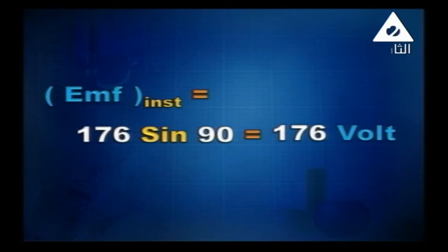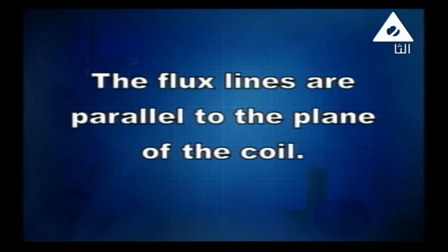Maximum EMF happens, yes, in the instant when the coil is in the horizontal position, where the plane of the coil is parallel to the field. Okay, so the flux lines are parallel to the plane of the coil. The coil is in the horizontal position.